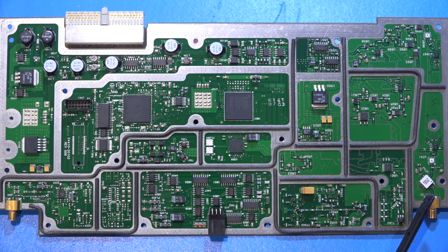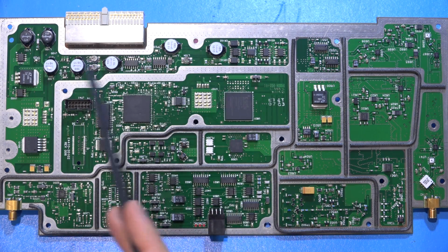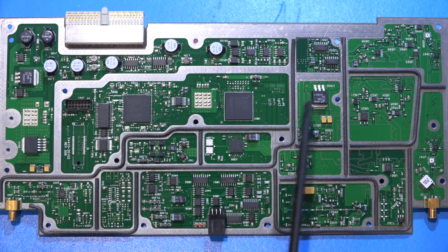Now we also know that there has to be a ton of selectors and so on, and we have to find where those selectors and switches and attenuators and VCO is. There is a block here that's unpopulated. This may have been some kind of DC-DC converter maybe, or some kind of an oscillator. It does have some very large pins here. Not sure what it is, but anyway, it doesn't need it anyway. There are lots of power conditioning and filtering and DC-DC converters you can see over here, and voltage regulators spread around, and you need those for various reasons I've talked about quite a bit. This is a programming port for the FPGAs.